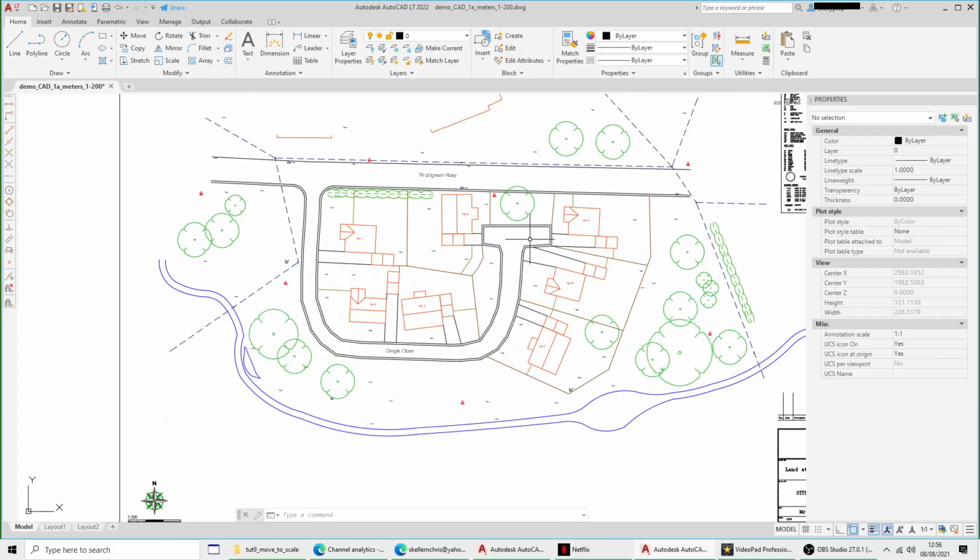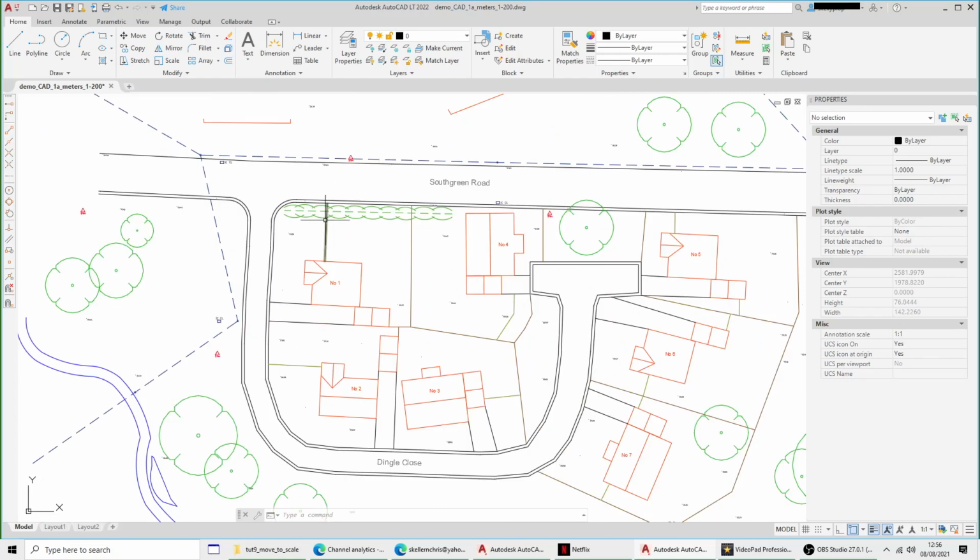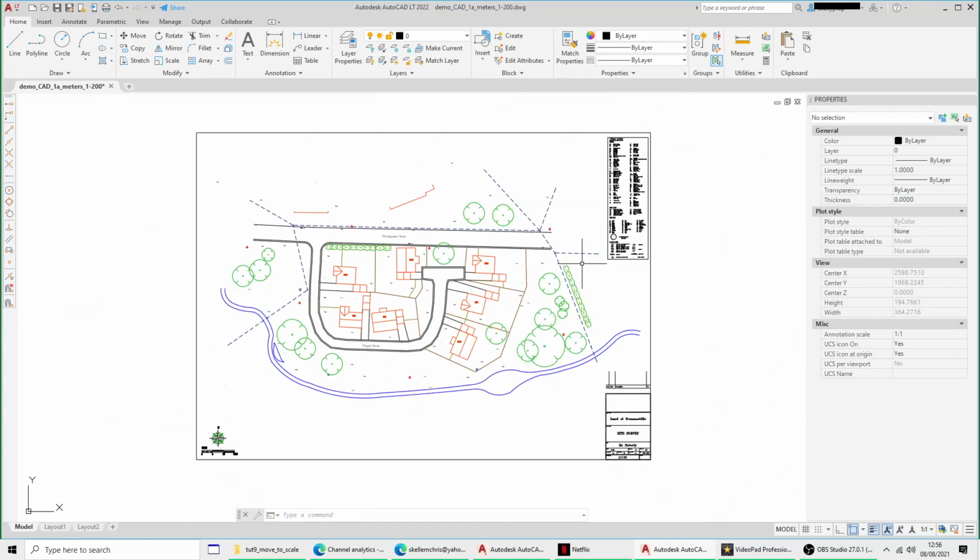And afterwards you need to check, run some basic checks, measure a few things and make sure it looks correct. And cover yourself with the client with a caveat, say the drawing was supplied scaled and I've used the scale bar or whatever to put it back to 1:1.